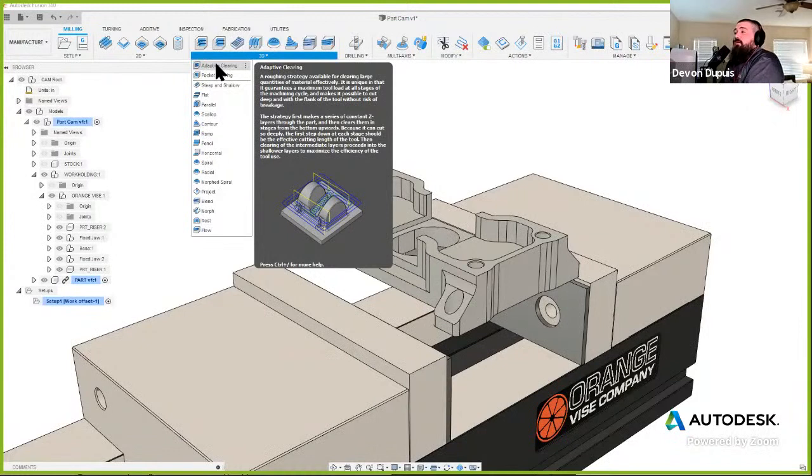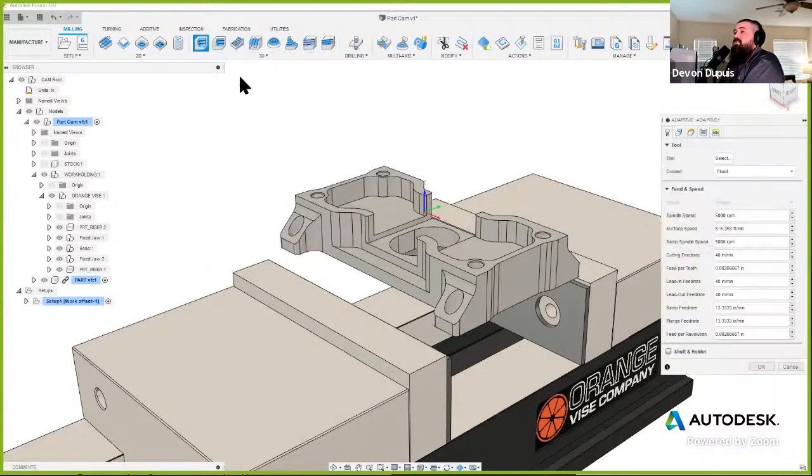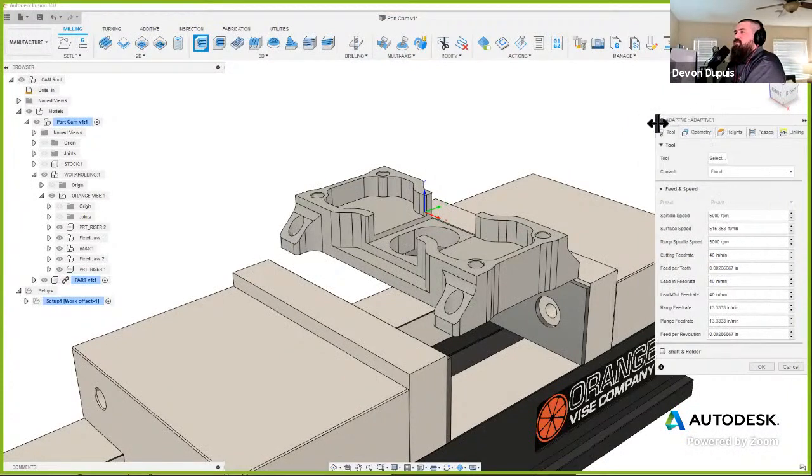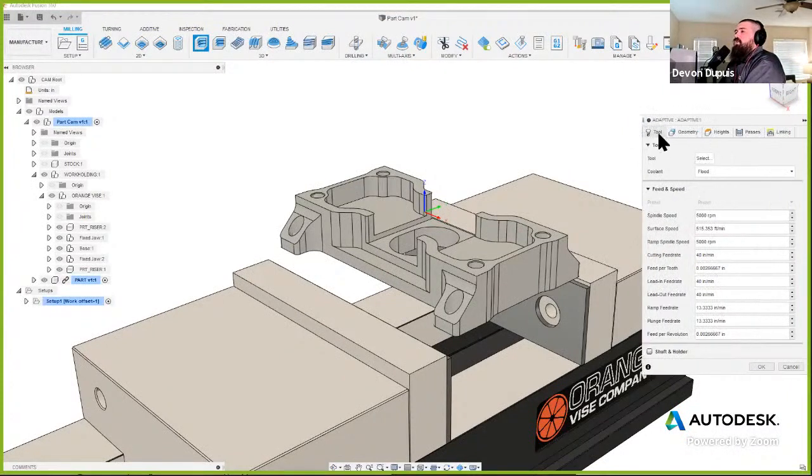3D toolpaths, however, are really kind of the opposite. By default, they know the stock, they know what the geometry is, in the case of this roughing operation here, and it's going to try to machine whatever we put in there. So without having many selections in here, we can just create the toolpath. I like to drag this little window out. It helps new users figure out what these settings are. So you see here, it shows little icons. If you drag this and make it a little bit bigger though, it's going to show you what these pages mean.